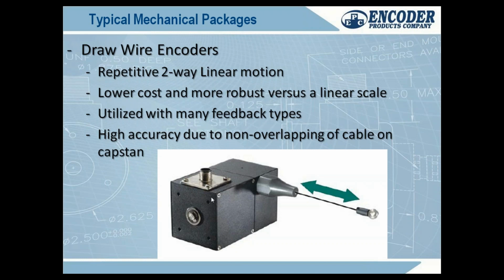One advantage of draw wire measurement, using an encoder for linear measurement here, is you can take the electronics away from vibration and away from heat. In the case of an injection mold machine, they're mounting this to that sled that the injector's on, injecting the plastic. Now they can move this encoder many feet away from the heat of that injector so that they're not cooking the electronics anymore. The forklift application, I've seen these used. In fact, I bet more forklifts are using draw wires now than are using rack and pinion. It's because it's repeatable and they can put it in the base and my encoder isn't moving with the telescopes. They are a very cost-effective solution versus linear scales.